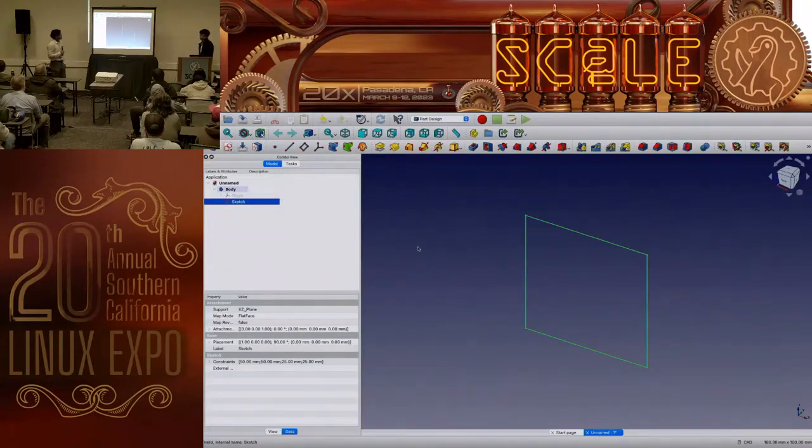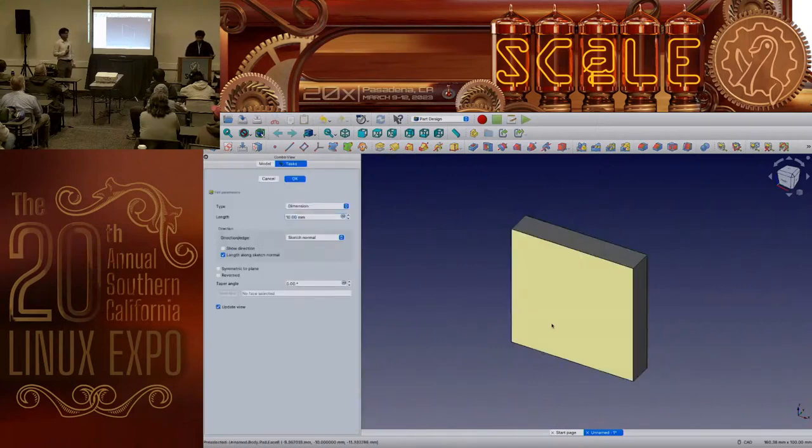And you see we have this sketch that we just created, which is a perfect square. Since we're trying to create a trash can, we still need to bring out the depth, make it 3D, correct? So what we're going to do, we have our sketch, and we're going to select pad. See that? It says pad. Basically, what this does is extrude your sketch, meaning makes it 3D. So now we have a 3D object.